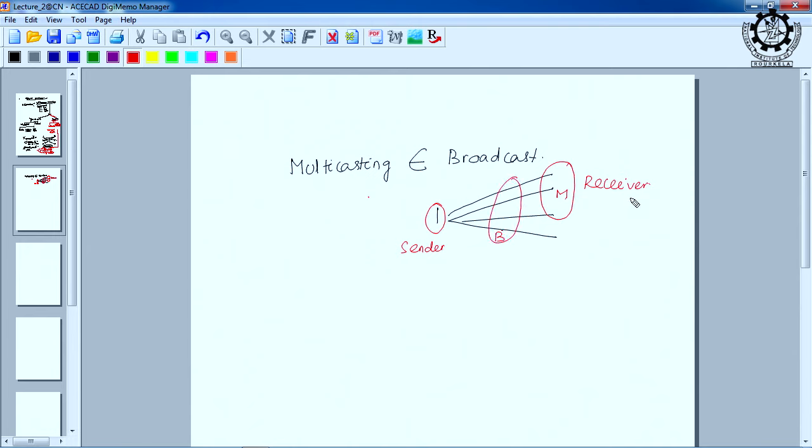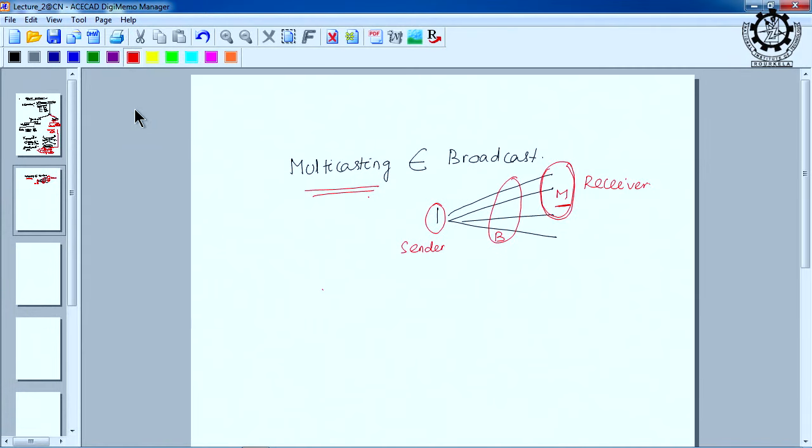You understand the difference between the multicast and the broadcast. So, how this multicasting is done? How a group is identified among all? Those are the issues in the multicasting communication. So, either you have a point to point, one on one, you have a broadcast, one to all, and a multicast, one to many. These are the mode of transmissions. Now, if this is given to you as a hardware designer, you decide how you will have a topology on this.